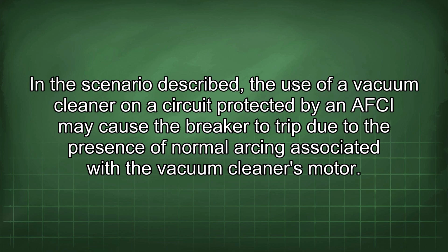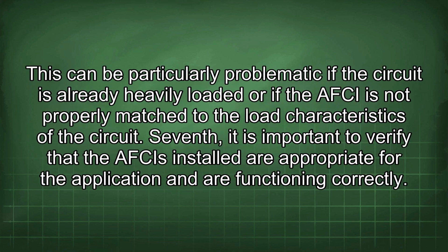In the scenario described, the use of a vacuum cleaner on a circuit protected by an AFCI may cause the breaker to trip due to the presence of normal arcing associated with the vacuum cleaner's motor. This can be particularly problematic if the circuit is already heavily loaded or if the AFCI is not properly matched to the load characteristics of the circuit.